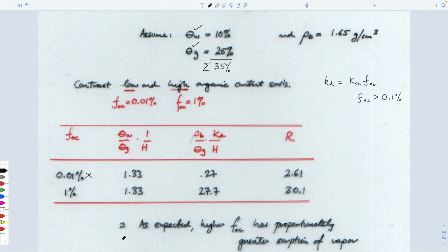But I guess I'm not sure what the point of this table is, other than to say, obviously, the magnitude of the aqueous concentration or the retardation is hugely controlled by the distribution coefficient, which is controlled by the amount of carbon in the system. A lot of carbon, there's a huge retardation. Not very much carbon, there's none. Makes sense. And the part that is the partitioning from the gas to the water isn't affected whatsoever.